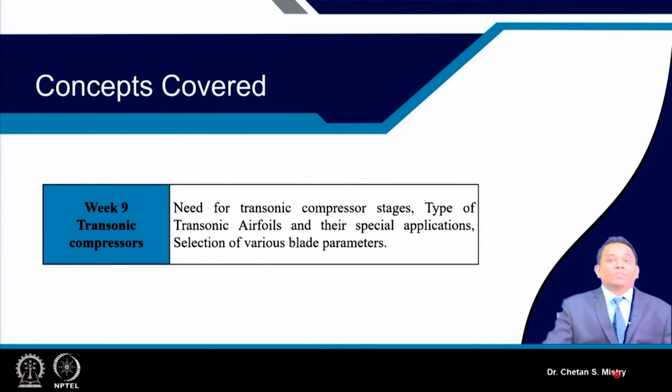Under those circumstances this does not work fine, and that is the reason why we give some rounding at the leading edge, as well as, when required, rounding at the trailing edge. Then we were discussing different kinds of aerofoils we will be using for transonic compressors. We realized those aerofoils are thin aerofoils. Basically we are managing our shock within the flow passage, and that gives us benefit in getting higher and higher pressure rise.